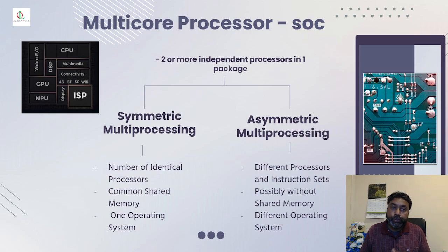When we talk about SOC, it is about multi-core processing. Multi-core meaning two or more processors in one package. Like in this example here, this is one full package which has the ISP, the image signal processing. It's got a general processing unit. It has got multimedia, DSP, CPU. So everything is built in, more than one processor in that, to perform its operations in one cycle.